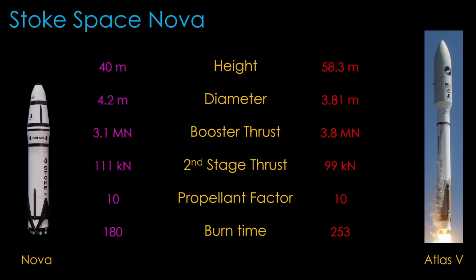That means the second stage has to do about as much work as the Falcon 9 second stage does, but do it with much less thrust, much less delta V, and a requirement to reserve fuel to come back to Earth and land. That doesn't seem possible with any useful payload, and pretty clearly Stoke is planning on carrying payload, so that means the numbers are wrong, I'm missing something, or both. The Stoke information is great to see, but it raises more questions than it answers. I can't evaluate their approach without information that makes sense, so you'll have to settle for my subjective opinion.